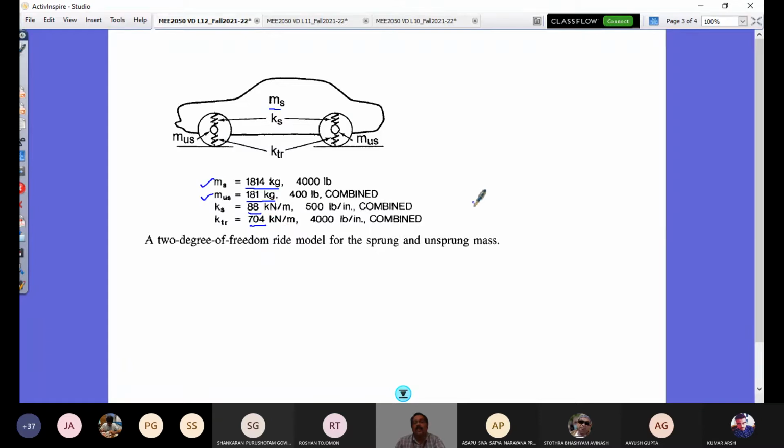Similarly, for the shock absorber coefficient and the tire coefficient, this should be approximately 0.2 to 0.5. So what is this coefficient's unit? It is Newton second per meter, because this coefficient is multiplied by velocity, and you get force. So remember this unit. If I multiply this by meter per second, the seconds and meters cancel, and I get force. So this is the damping coefficient for the shock absorber. But if you compare this value to that of a tire coefficient, that's insignificant.